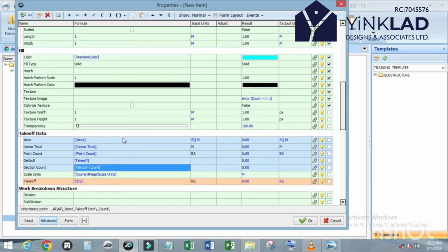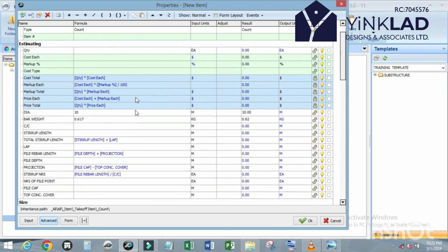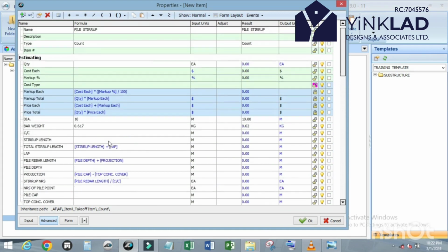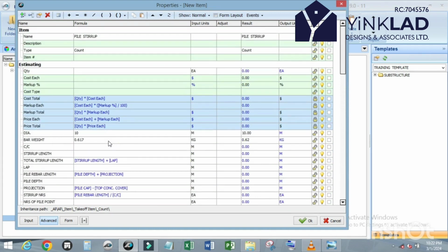Yeah. So now I want to double check. I don't want any issue with this. That's why, so that someone will not come back at my comment section box that, oh, you mixed it up, something like that. So now diameter 10 mm. I mean 10, yeah, no, meter is mm. That's why you have to double check anything you do. So 10 mm, bar weight in kg. The kg of 10 mm is 0.61 approximately.